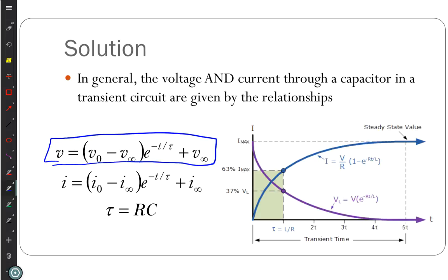You keep saying transient circuit. I'm a little unclear of the definition. Okay, so transient means you're changing between one state and another state. So we have DC steady states, is all that we studied up to yesterday. And then transient is changing from one DC steady state to another DC steady state, but it's not steady in between. And so that's what the transient is. So is it only transient while it's changing? Yes.